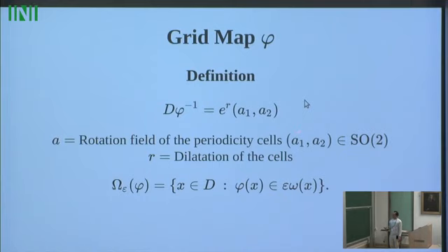In the previous slides, omega was independent of x, but if you want to change slightly the kind of microstructure you are using depending on the position x, basically the size of the rectangular hole, you can choose this omega depending on x. And it's quite easy to prove that in this case this shape does indeed converge toward the composite shape that you want to obtain.